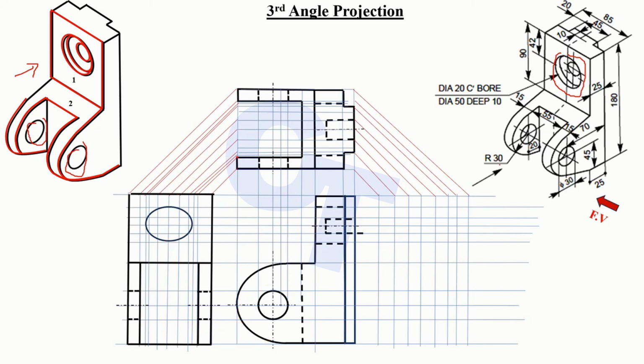Okay, so the radius of that circle is going to be 25. And there's a small circle that you can see, and that one has a radius of 20, right? So I said you can draw a line right here. I'm going to draw them, but I'm not going to see them because they are at the back of our diagram. So I'm going to indicate them using some hidden details. They're going to run from top to down, right there.